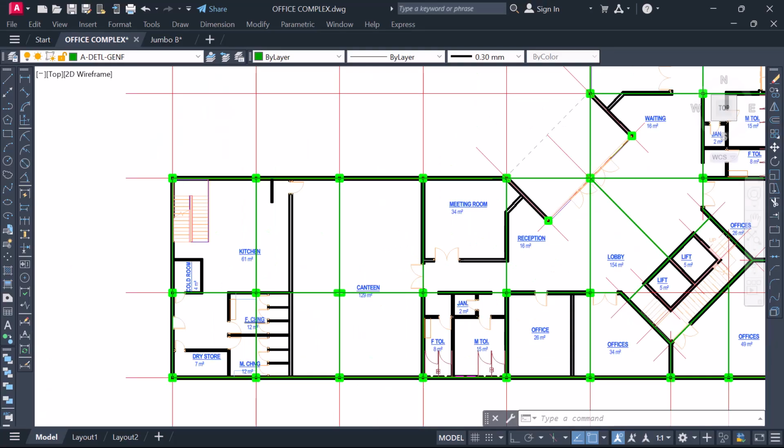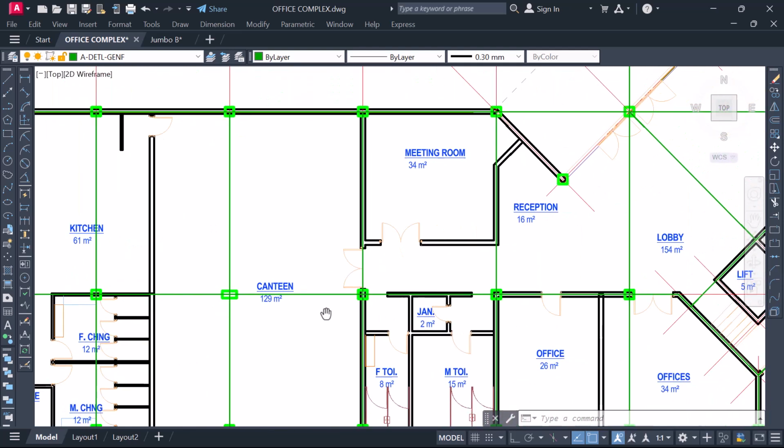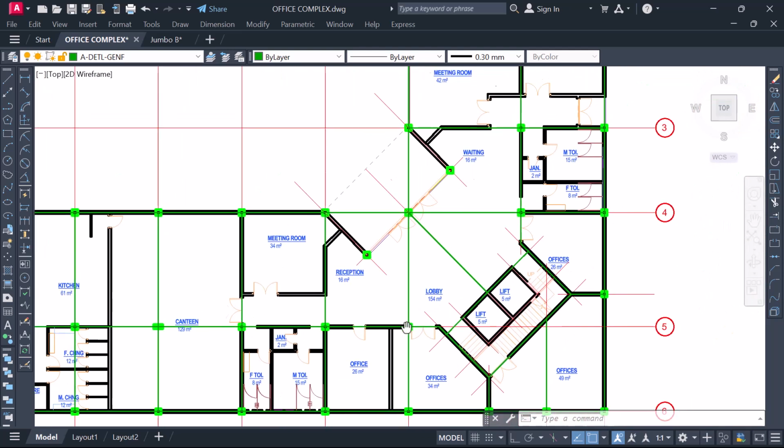That's one. Two, if you intend to provide structural walls around the staircase and all that, then step two is when you are meant to do all that. Then your slab structure, how your slabs are going to be paneled and all that, it all falls on this step two. Step two also falls on how to carry the upper stories, so you also think about that in the structural framing.